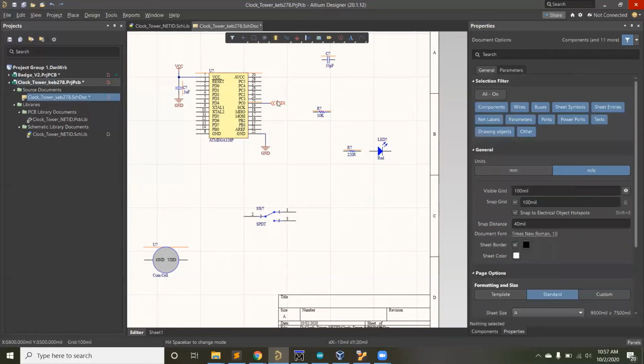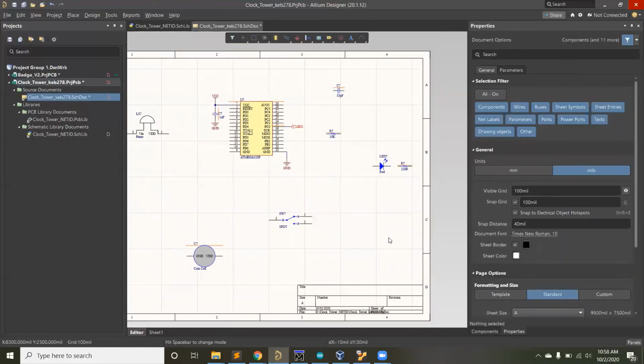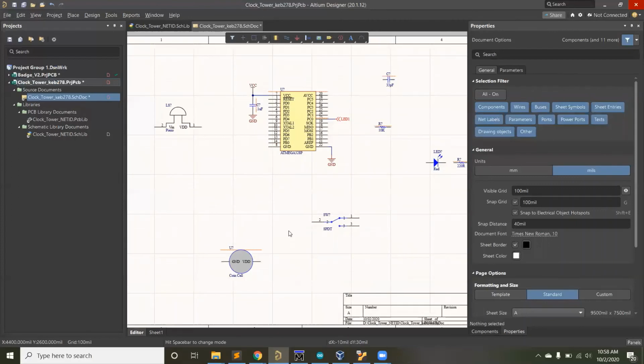Drive these again from here, so you can connect this to here. And you'll want to make sure that current is flowing from positive to negative. You can do this one of two ways. You can either connect this to VDD on this side, and then have it flowing to a pin which will go high or low. You can connect it to ground or VDD, or the opposite way around. It doesn't actually matter. These can pull high or low, so do it either way you like. You can connect this directly to power or ground, but don't connect it to both, because then you need to be connected to the microcontroller on one side to control whether or not they're on or off. Okay, so I hope that makes sense.